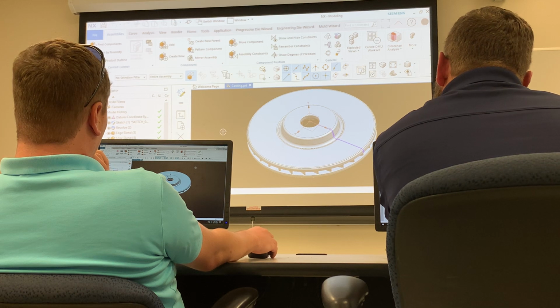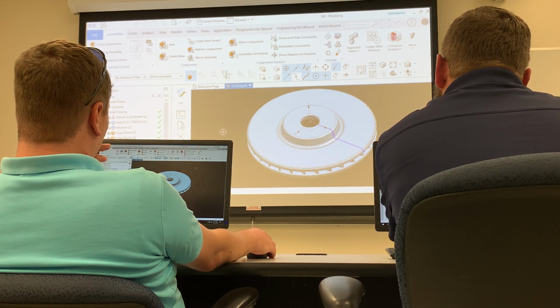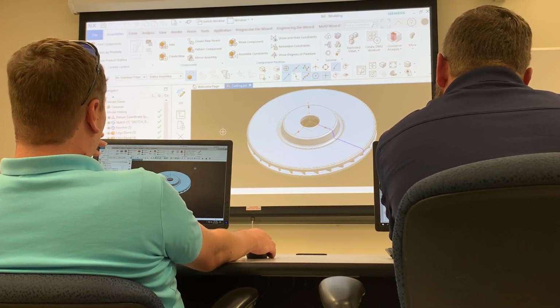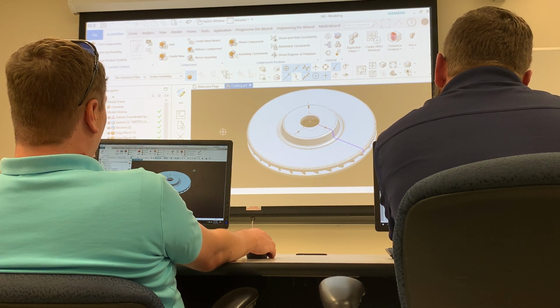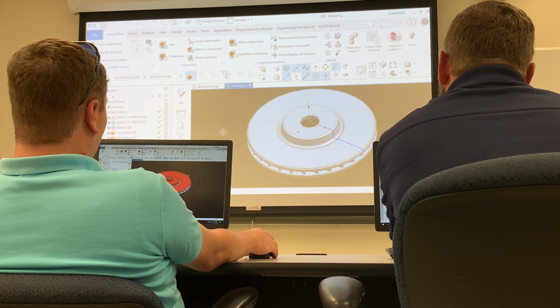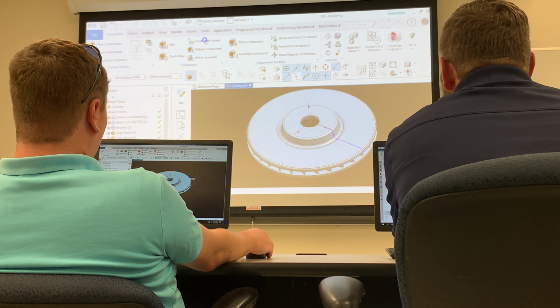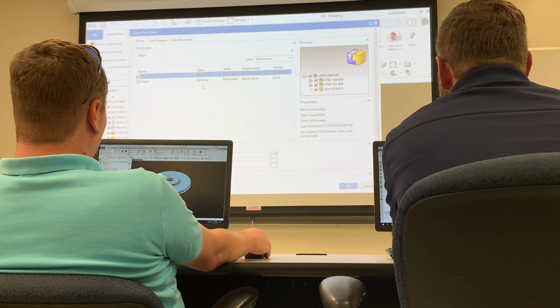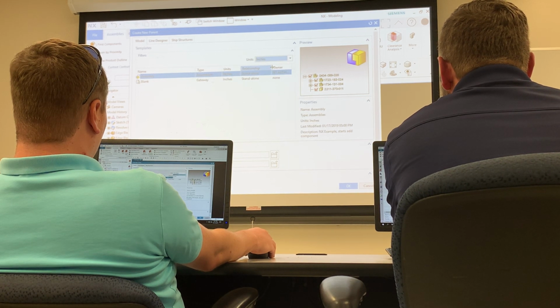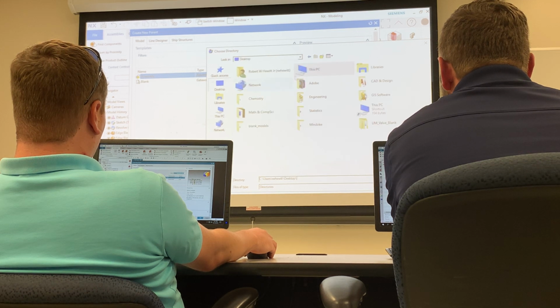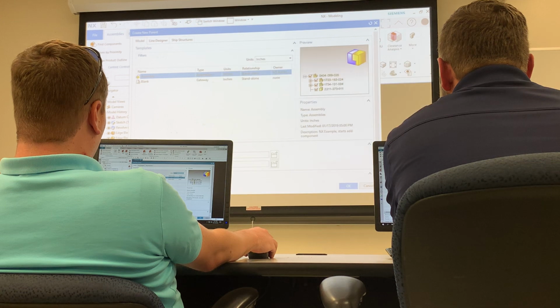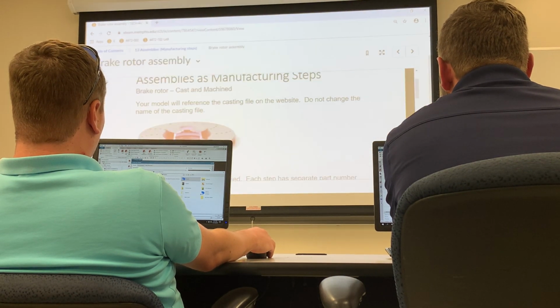If we're at this level and we realize, wait a minute, this is actually a component in a higher level assembly, what do we do? Create parent? Yeah, new parent. Create new parent. We're going to create it in inches, even though that first model is in mm. And we're going to make sure to keep these in the same directory. I put mine on the desktop, so this should be on the desktop as well. And you need to give it the name.